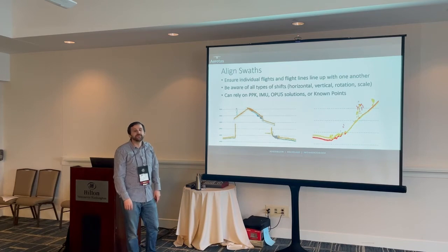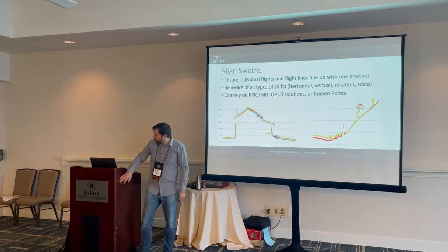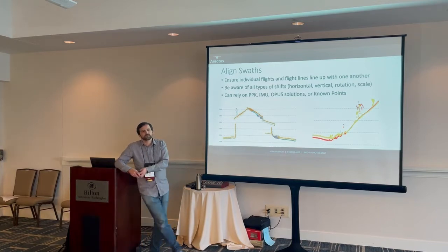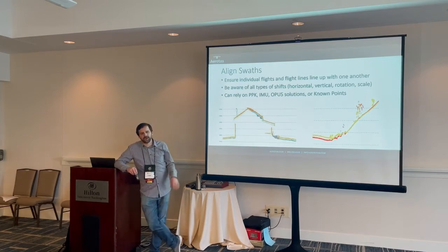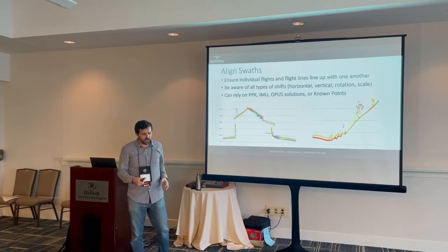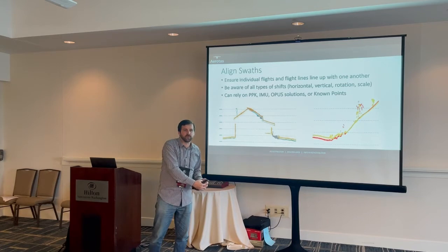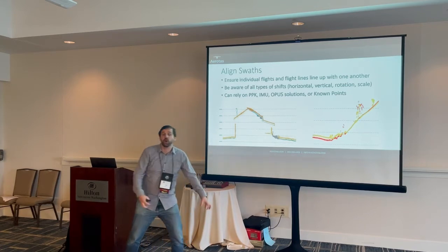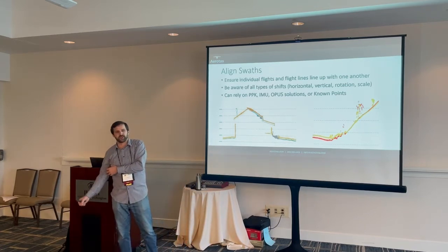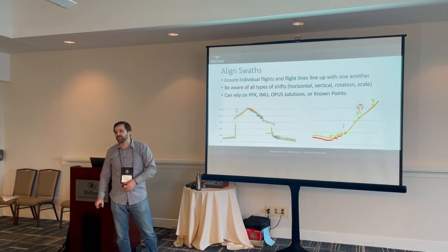Follow-up question to what he was saying. So the proprietary software that comes with the LiDAR units does not cover overlap corrections? Yeah, typically not. And again, this depends on how you do it, how your base station is set up, how you're streaming corrections, whether you're localized, whether you have your base station set up over a known point that already has an OPUS solution that you've already calculated, or whether you need to post-process the location of that base station and shift it after the fact.